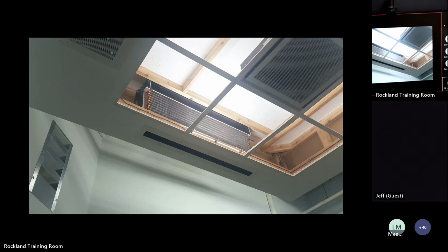Okay. So peeking back behind that slot, this is in our tech center. This was not an actual project. I know we've got exposed wood, combustible, right? But this is just for display purposes only. You can see that you've got that recessed unit coupled very closely to that slot diffuser. So architecturally, you could align that to any sort of linear slot diffuser and match the aesthetic requirements in the space, but still get that chilled beam installed.